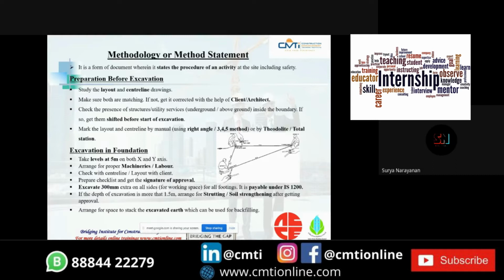And marking the layout and center line by manual method as well as by instrumental method, where the manual method includes the right angle method or 3, 4, 5 method. So it is also known as the Pythagoras theorem method. And by instrumental, we can use theodolite and total station for marking.